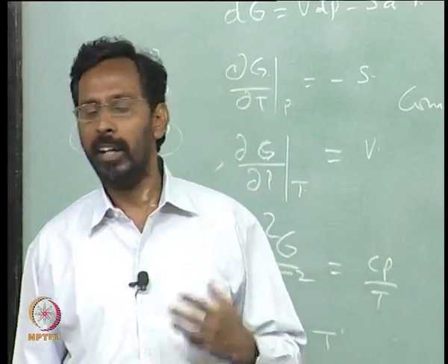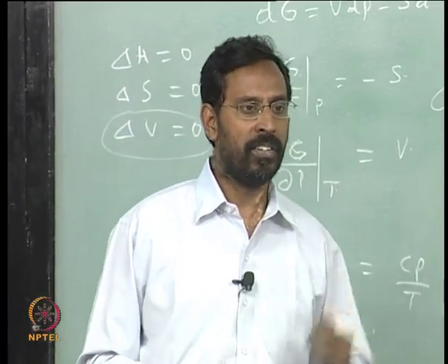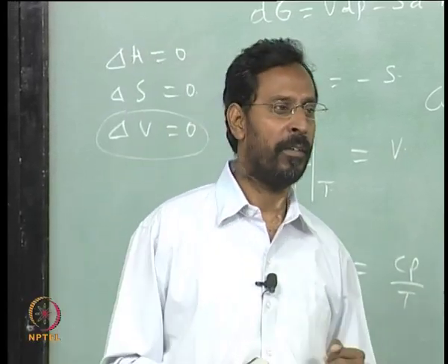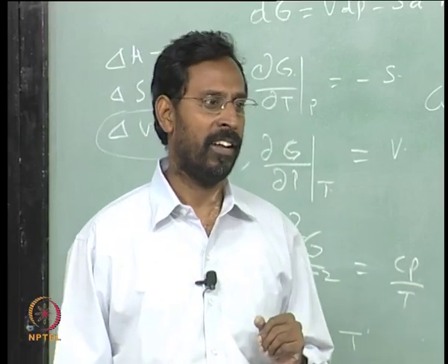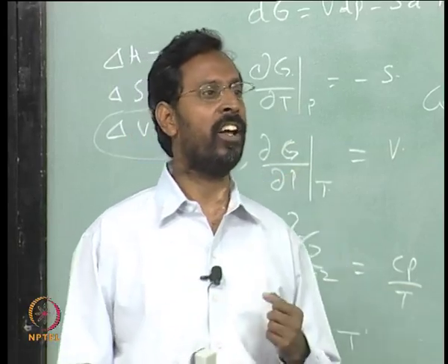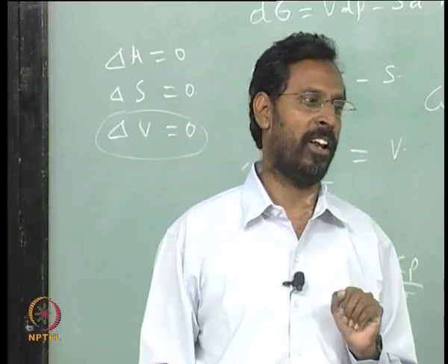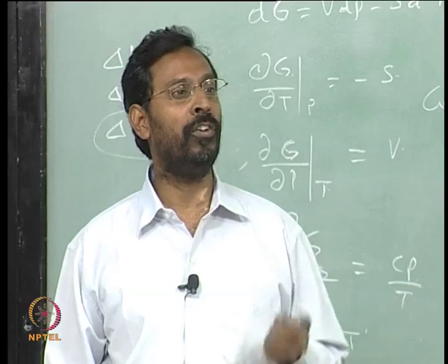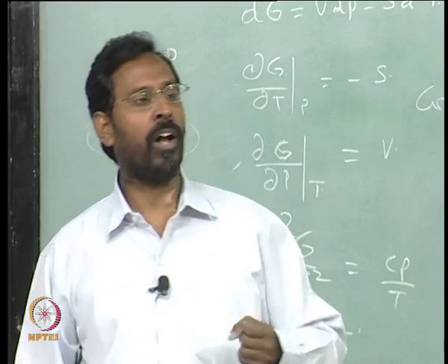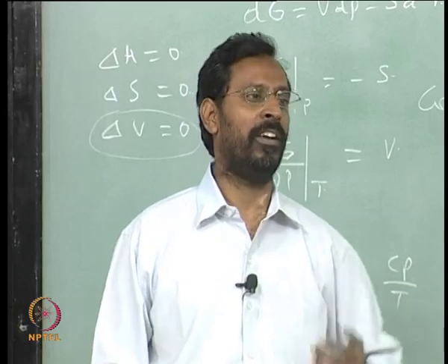So, what they have done in these bulk metallic glasses is they have added a large number of elements. Instead of just a binary alloy, they made a 5 component or a 6 component alloy. Once you have this many elements inside the liquid, for a unit cell to form and for a nucleus of critical size, r star, to form and grow, all these 6 elements have to sit inside the unit cell. This is what we call the confusion principle. Because of that, it becomes more difficult for the liquid to nucleate a solid. As a result you can easily undercool the liquid.